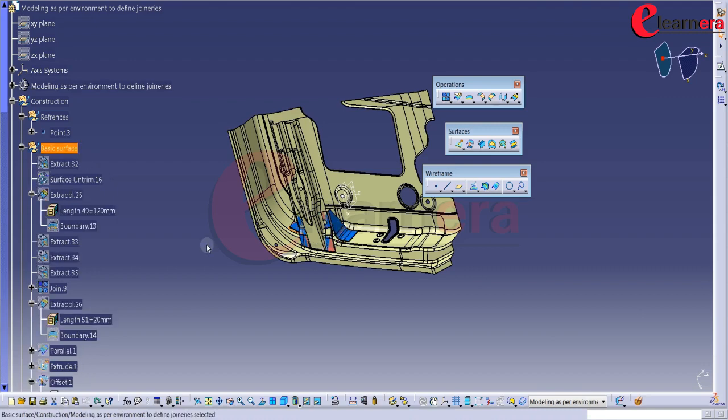Now we will see another technique of removing geometrical set. If you wish to remove the geometrical set but wish to maintain the content, do the following. This is only possible if the geometrical set's father location is another geometrical set. When the father location is a root geometrical set, then this is not possible.